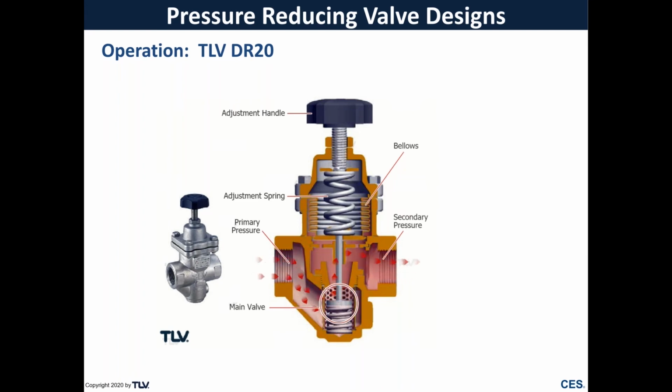As pressure builds downstream, equalizing occurs by feeding the downstream pressure to the underside of the adjustment spring against the bellows, where its upward force counterbalances against the spring compression. The adjustment spring compressive force, which opens the valve, is limited to allow sufficient spring sensitivity to equalize with downstream pressure changes. The net result is simple pressure control through a valve orifice, but where high flow rates result in a drop-off in secondary pressure.